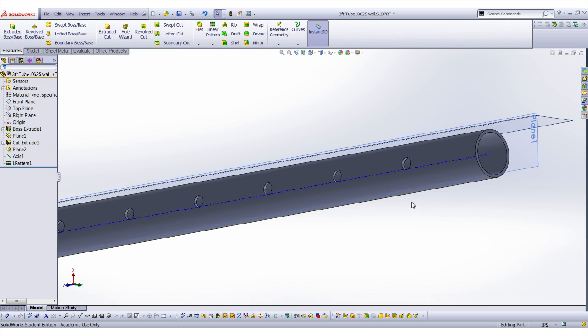You put holes in it, then you saved it as a flute. So the long pole itself had holes in it because SolidWorks just knows that it was the long pole the whole time. So now if you go open flute, it knows the different part. Wait, if I open long pole, will it put holes in it now? It'll have the suppressed part that you just had. Like you can delete that part and it won't have holes in it anymore. But you can open flute, it'll be different because the save as is where that tree basically branches. Everything before that save as, you were modifying the same part.